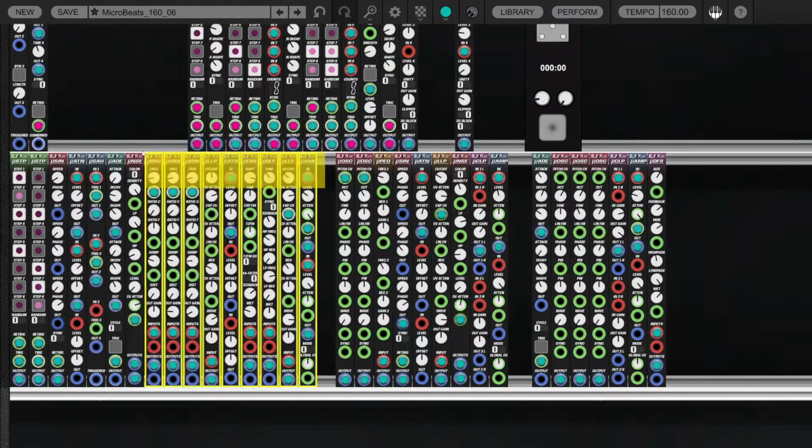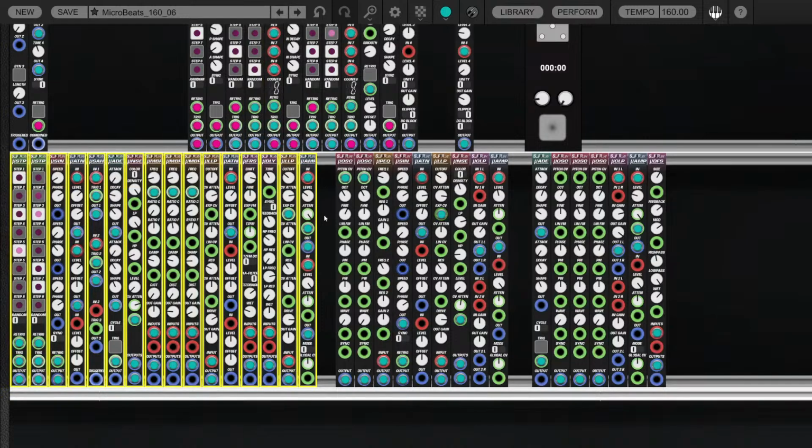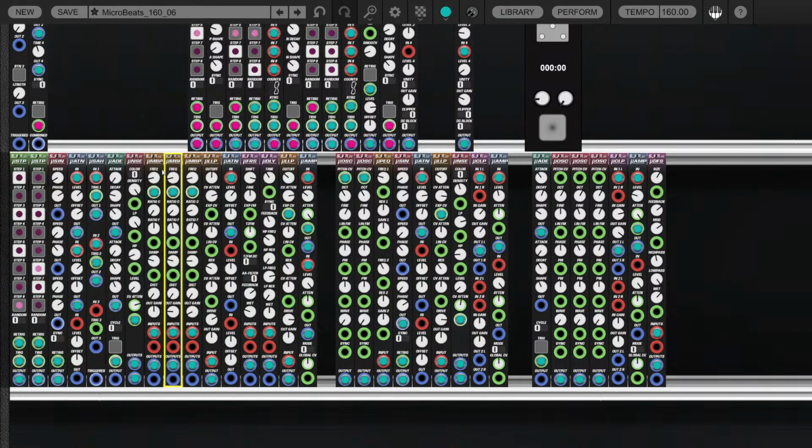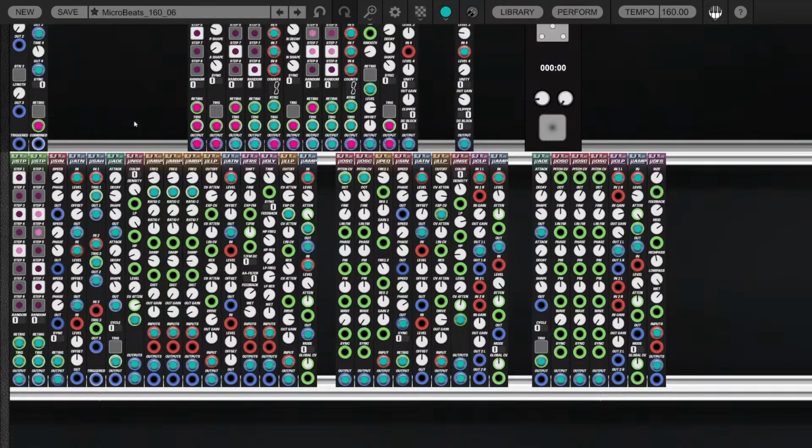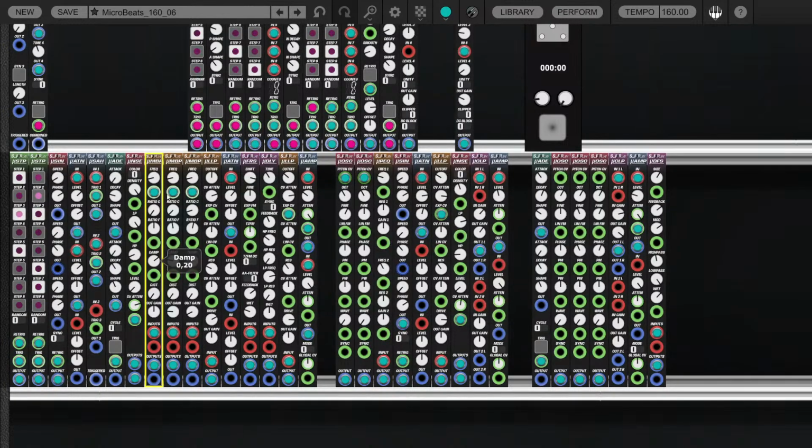Let's go down here. We have our physically modeling patch using modal bandpass filter. Modal bandpass filter is in essence a very high resonant bandpass filter that rings out. You can set the ring with the dampening. If you turn the dampening down, it rings out more. If you pull it up, it rings out less. It's kind of hard to show now because